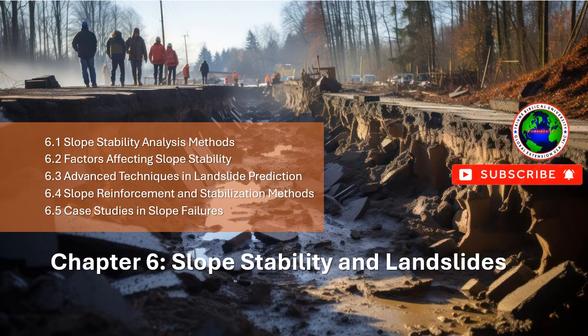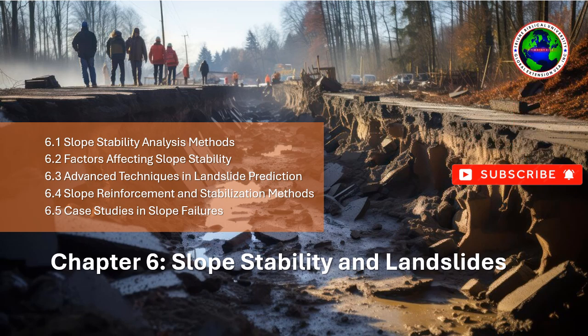Slope height. Taller slopes are more prone to failure because they have a larger volume of material and increased driving forces. Tall slopes are also more likely to experience large deformations due to gravitational forces.